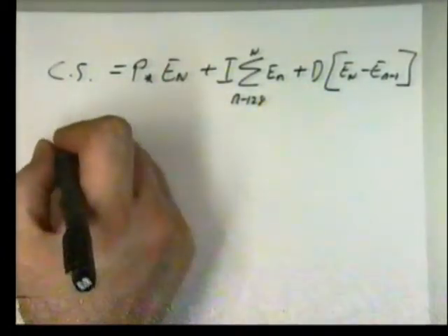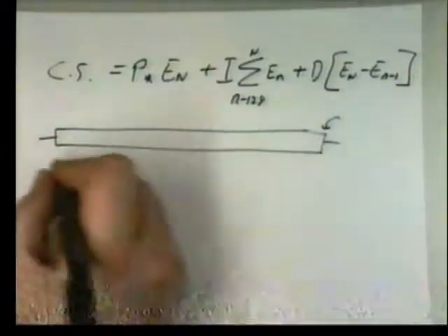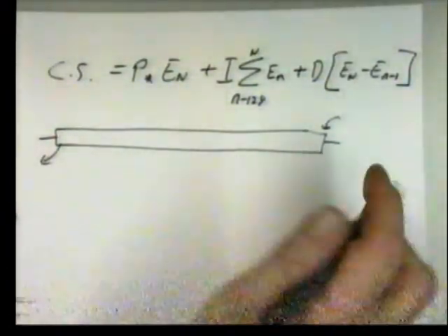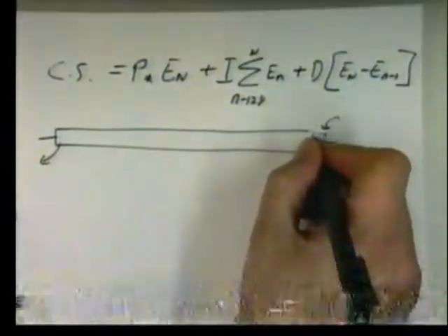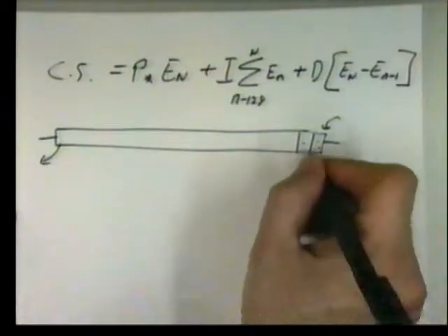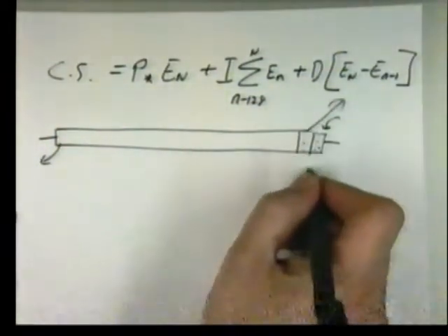And we do this all with our array. If we had a 128 element array, and we're always putting the latest reading into there and dropping the oldest one off, so it's a moving window in time. There's e(n), there's e(n-1), so we just take the difference between the last two readings in our array, which gives us our derivative term.